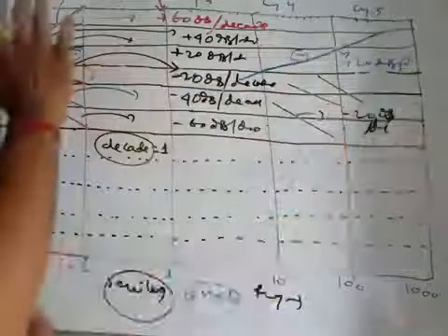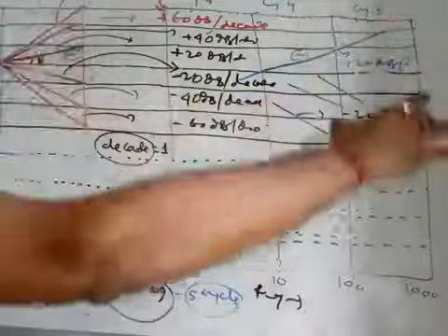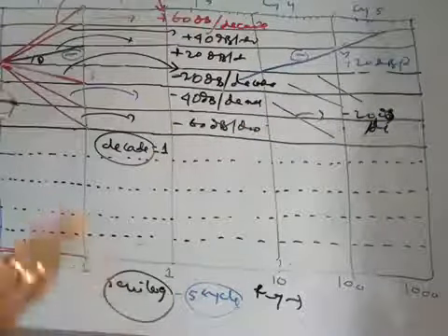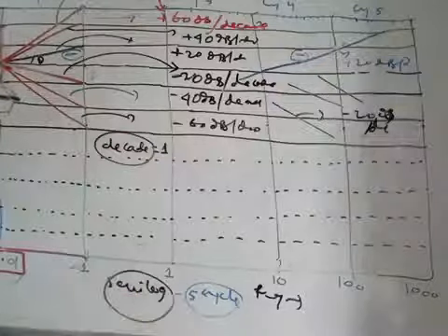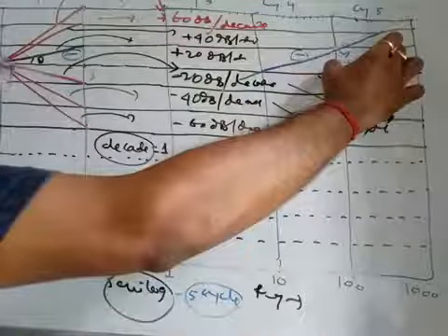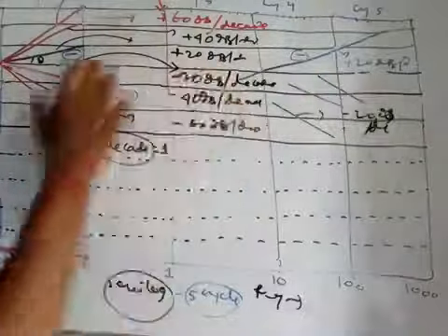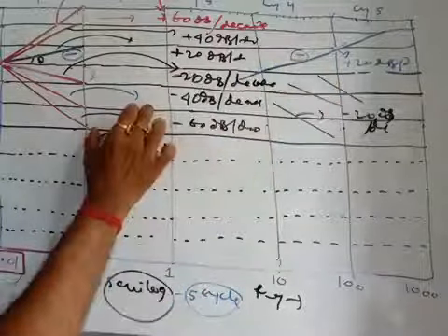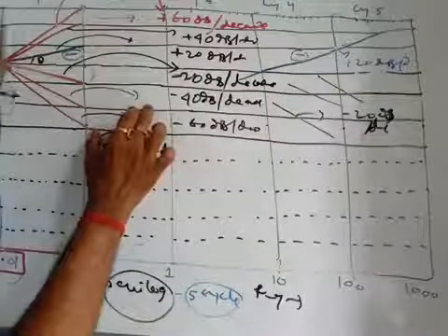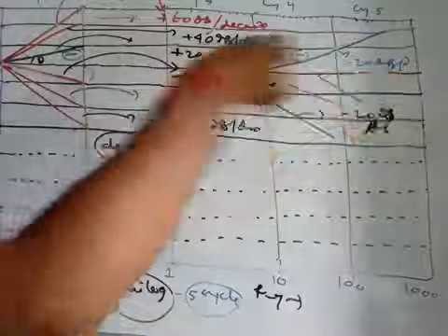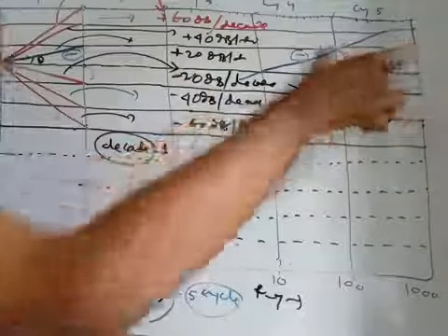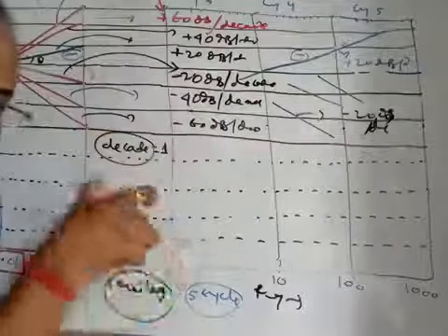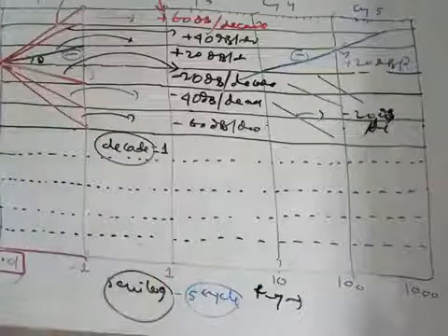So you will draw all these slopes here, right? Whenever you require any slope, say plus 20 dB per decade, we will just take the parallel line of that section anywhere in this graph, and it will indicate that its slope is plus 20 dB per decade. If you take the parallel line of minus 20 dB from here, you will get the minus 20 dB line anywhere. So that is the concept of this slope.